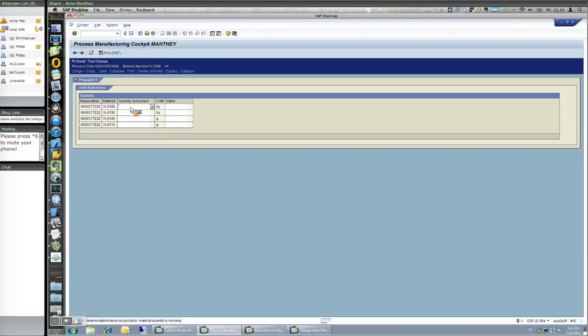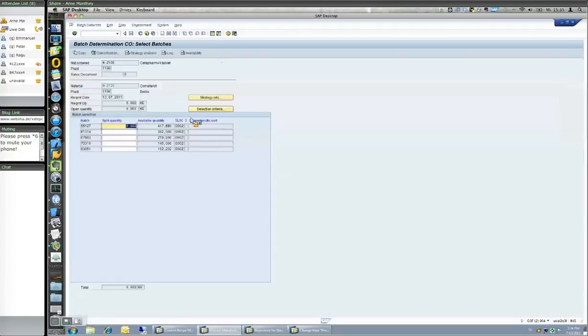finalizing the stuff. And the idea was that you enter live parameters in all of the three sub branches in your XSteps, and that you can set the values of a live parameter. As soon as the weighing dispensing is finished, you set the value of one live parameter, and this live parameter then triggers activities that allow you to start with the first phase of the steering PI sheet. This was the intentional idea because XSteps don't have those global variables, global parameters that you have in the old legacy mode.